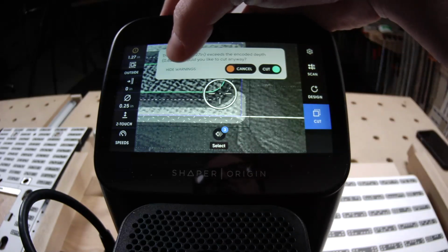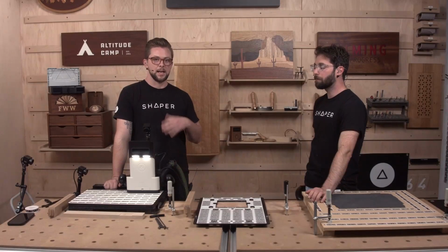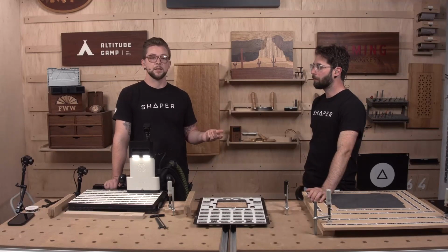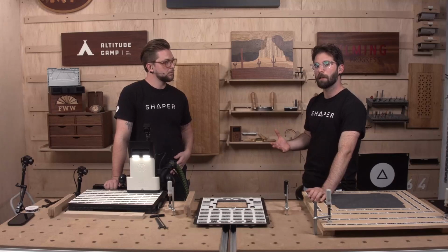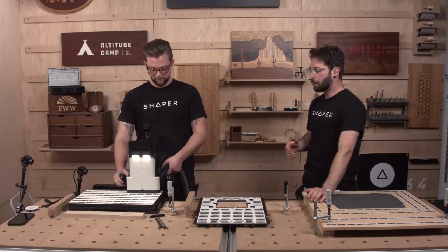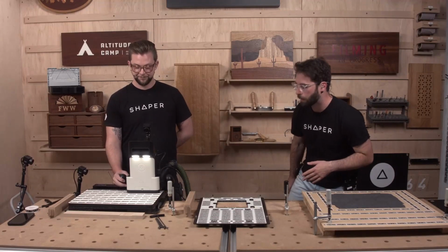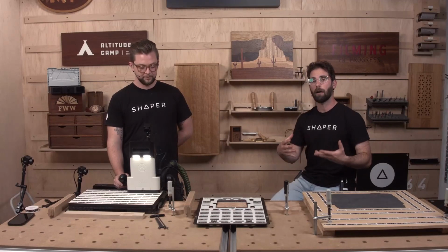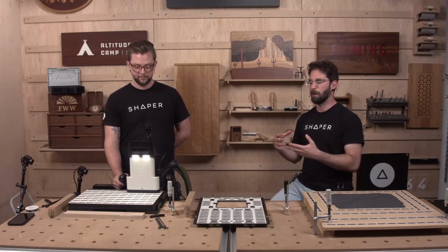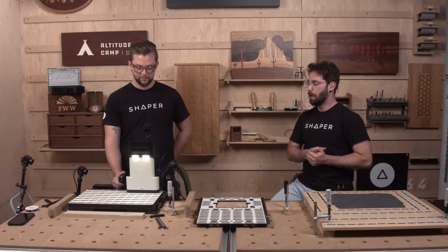You can cancel. You can hide the warnings, and basically, if you hit that hide warning sign, it's going to hide the warnings for the rest of your cut session, until you power cycle the tool. And so there are some situations where that warning is going to be very useful. The best use case is right here that Jake illustrated, where you have two cut paths really close to each other, and you don't want to mistake a shallower depth for a deeper depth pass.